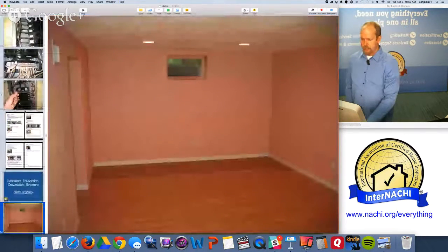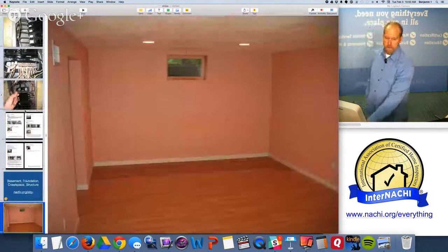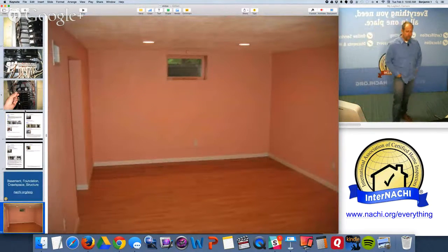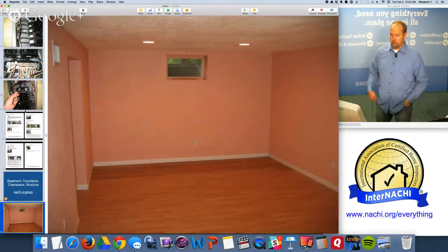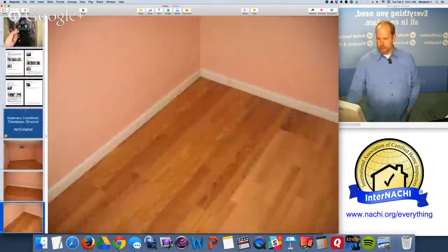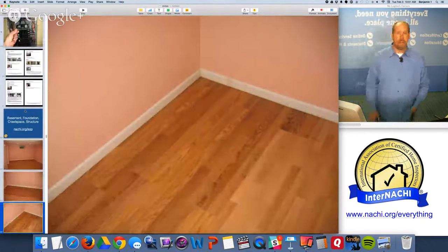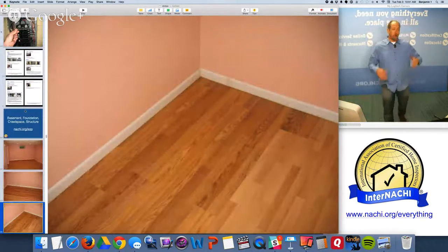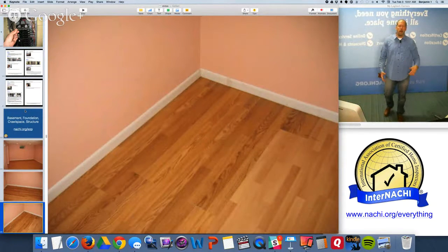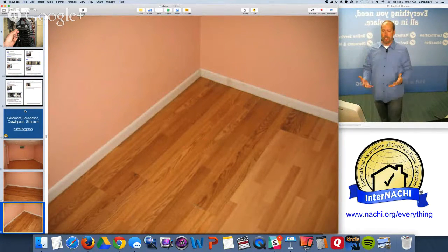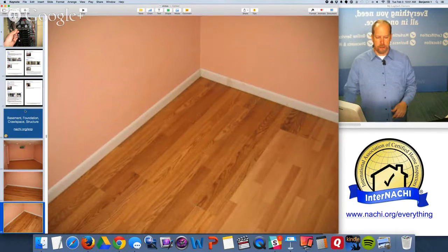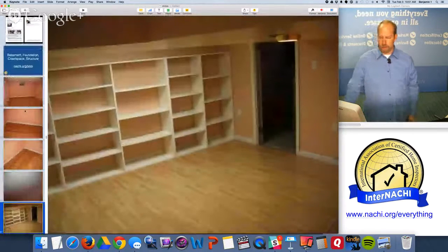Basement, foundation, structure, crawl space. So there's the basement, a finished basement. There's no egress for this. I need an emergency egress for this. This room here is essentially a bedroom, a living space. And I'm looking at anything where walls intersect floor and where walls intersect ceiling. I want to look for indications of water penetration, right? I want to look for watermarks.